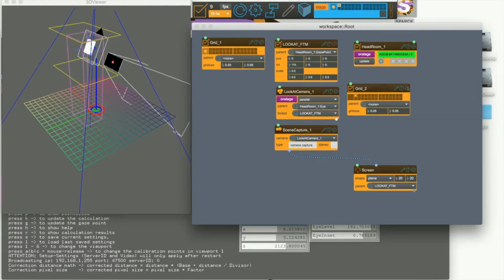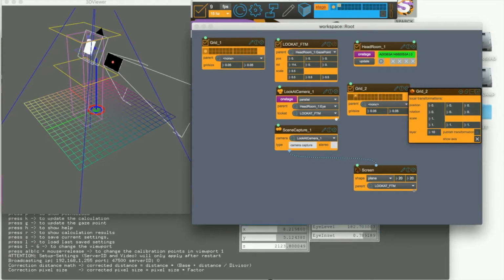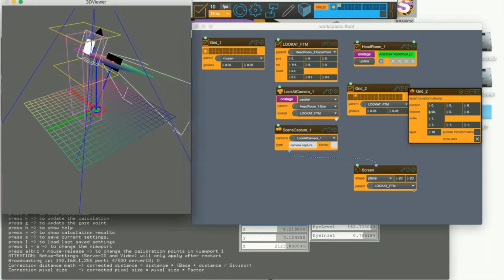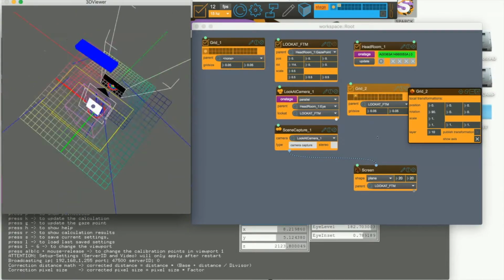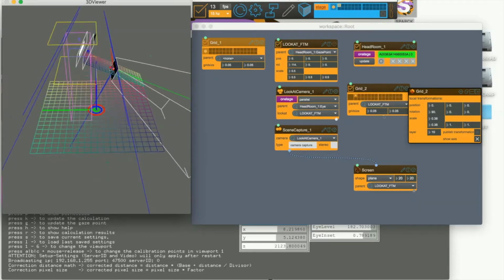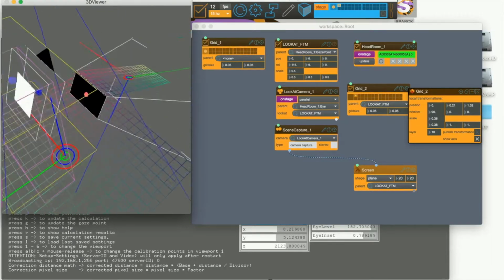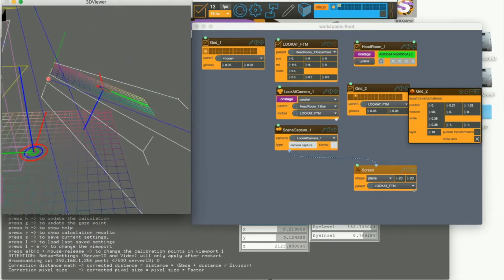and pin the property window, select a different transformation parent. Now I make a local transformation, turn it in at 90 degrees, and resize again, 0.38 in the width, and the height should be 1. I'll leave it at 1, and I drag it a bit to the back and up. So that looks cool.